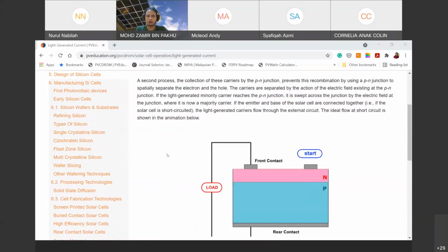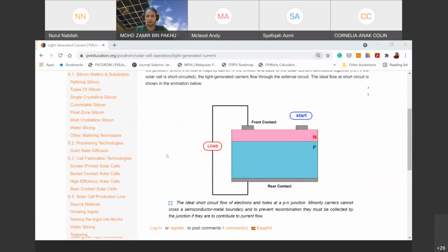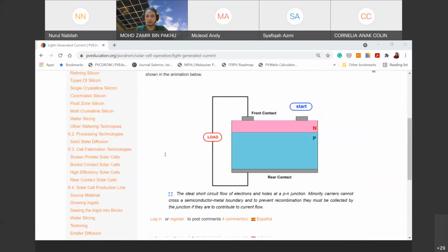So yesterday we talked about carrier generation and operation of solar cell briefly. So let me just show you an animation to illustrate so that you get to understand the mechanisms, right? So this is basically a structure of a solar cell. So it is a p-n junction. So in this case, you can see that P side is thicker. So that means the wafer is p-type, and then the n-type here is the emitter, the diffuse emitter, the thin layer on top of the wafer.